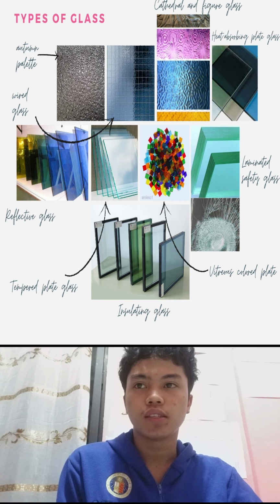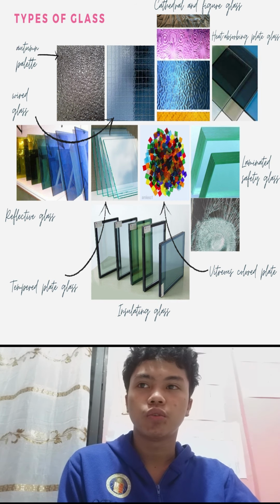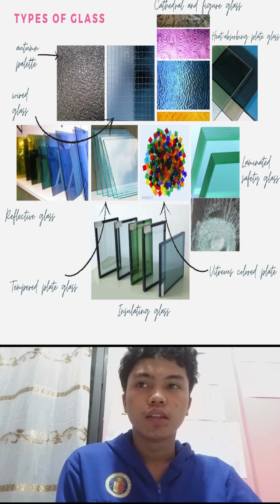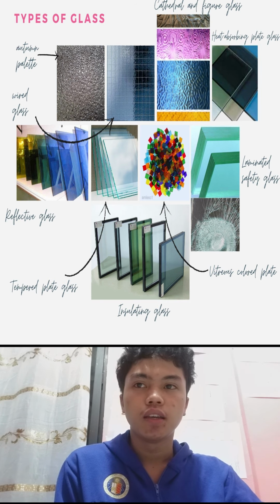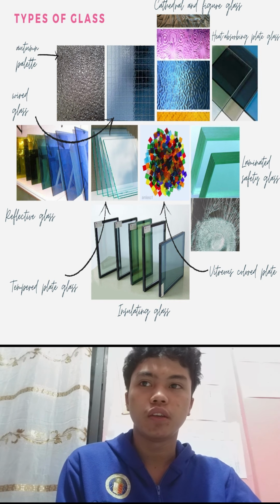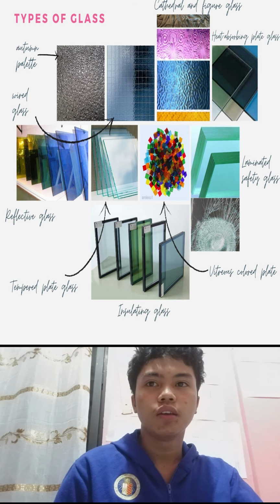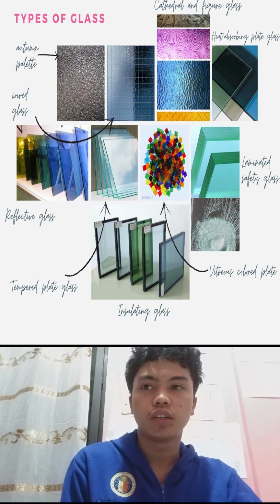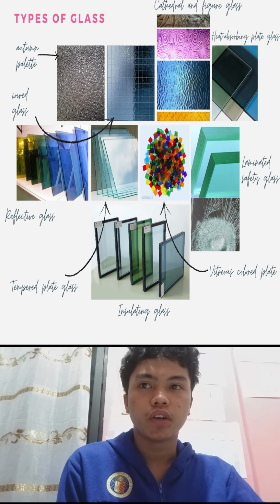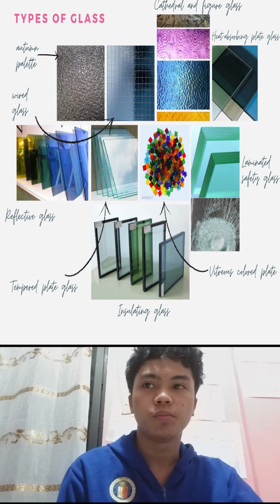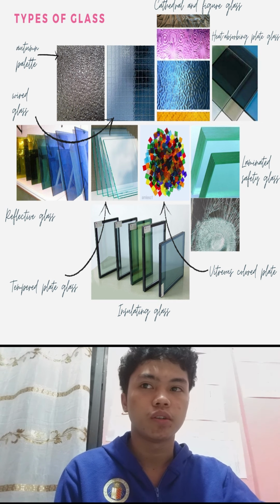The first type of glass is reflective glass. Reflective glass is the product of a glass coating vacuum chamber. The glass is coated with micro-thin layers of metallic films which provide the performance characteristics of the glass. It reduces solar heat gain by reflecting the sun's energy, resulting in savings in initial and operating costs of air conditioning. Manufactured in two types, silver and gold, the glass can be specified in any one of three nominal light transmittances of 8, 14, or 20%.